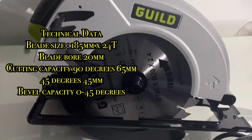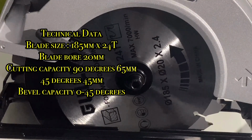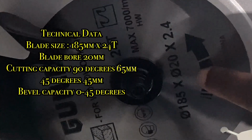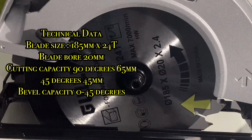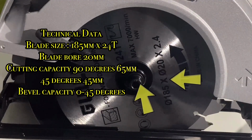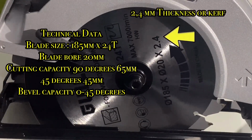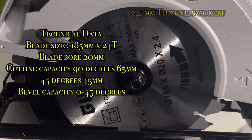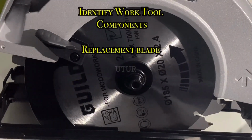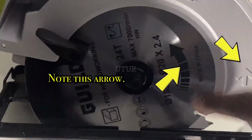If you juxtapose the technical data information side by side with the information that you've actually got on your blade, we can instantly begin to see that there is a correlation. 185 being the actual blade size or the size of the rim, 20mm being the blade bore, which is right at the center of the blade, and 2.4mm is the thickness or kerf of the blade. At a later stage, I will show you how to adjust your cutting and bevel capacity. The next step would be to familiarize with other work tool components.